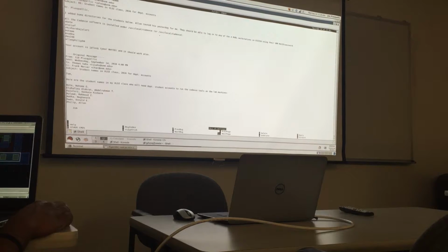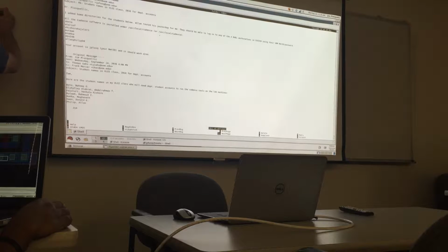This is called inherited connections. So you inherit the actual name from the parent. That's what inherited means. For the layout pin, it's brackets at, for ground, GND, colon, then a percent sign, then colon. Yes, that's right. GND, bang. So this is what it looks like.